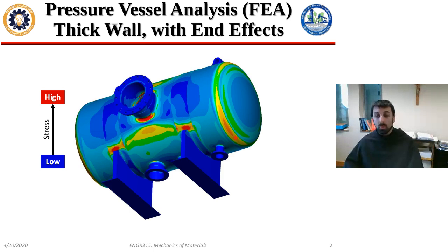We've only cut one section so far, but right now all we've seen is normal stress, and that's what we're going to continue to see. It's due to our thin walls assumption. Our walls cannot sustain any bending, which is also a fairly good assumption. That's why people put so much work into leveling the ground underneath the tanks, to make sure they don't settle.